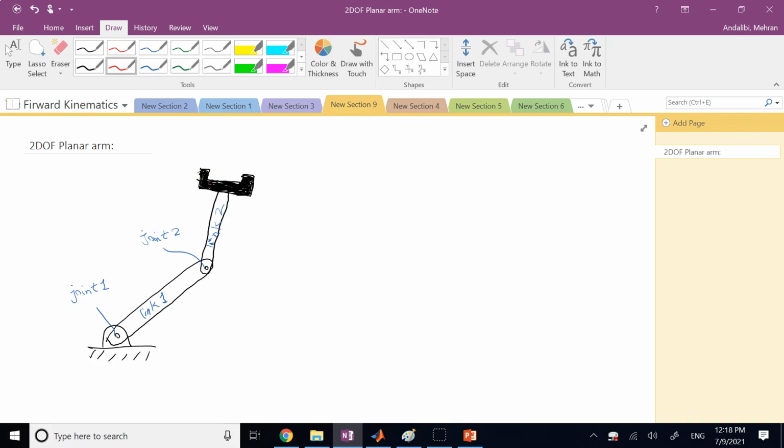Okay, the first thing it says is determine the actuation axes. So here you have 2 joints, there are 2 actuation axes. First joint 1, then joint 2. So we have 2 Z's. What are they? Clearly, both of the rotations are happening about axes perpendicular to the plane. So here, I show perpendicular to the plane toward me with a direction like this, and then for the other one, something similar like this, right? And let me try to make it as parallel as possible. Then what do we call these Z's? We are not going to call them Z1 and Z2. We are going to call them Z0 and Z1. As it says, Zi is the actuation for joint i plus 1, which you can see here. So for joint 1, the actuation axis is called Z0. For joint 2, it is called Z1. Where is Z2? We'll talk about it.